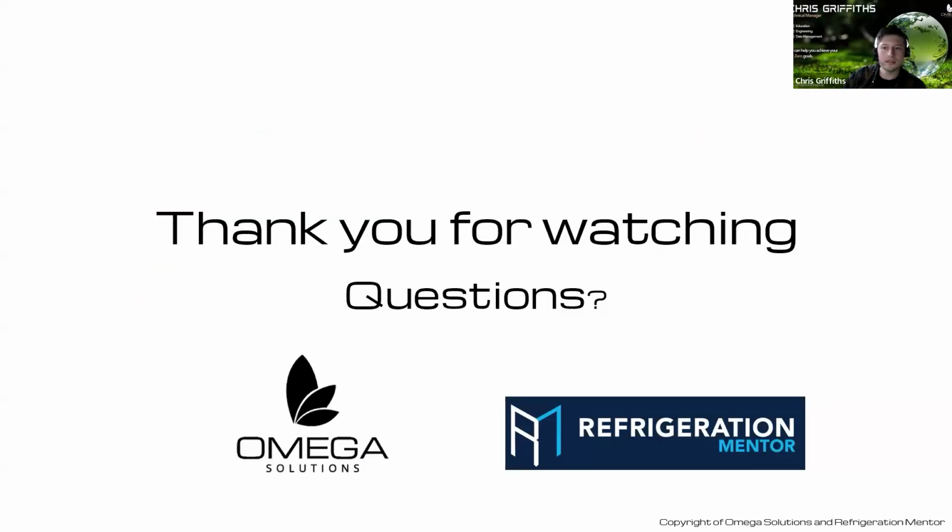So again, any questions? Yeah, there was one question by Andrew Freeber, a good friend of mine, been in tons of training, ambassador of the Refrigeration Mentor community. This would go back to the oil in the transducer. What would you recommend if you do have oil in the transducer? And he kind of answers, I feel like something needs to change, because if it happens, it's most likely to happen again. It's like anything. You don't want to put a TX bulb at the bottom of a pipe because oil is going to insulate it there.